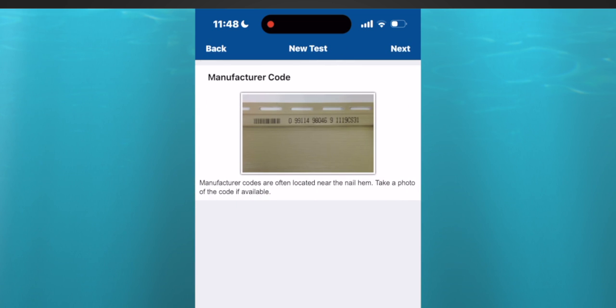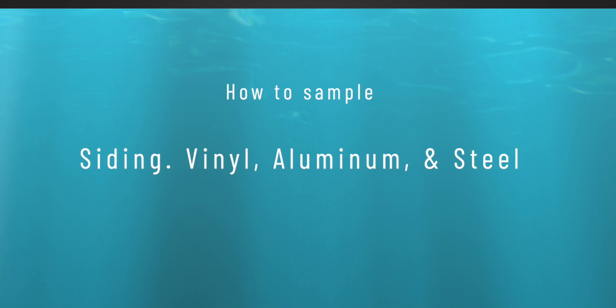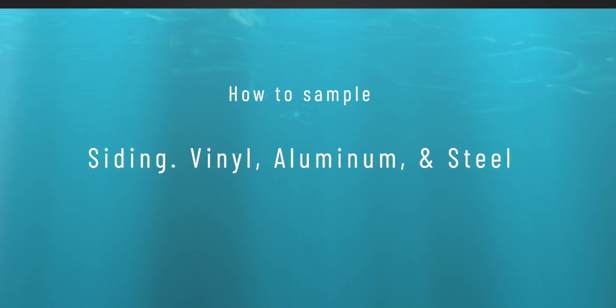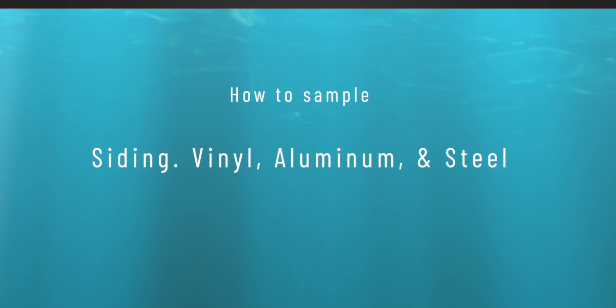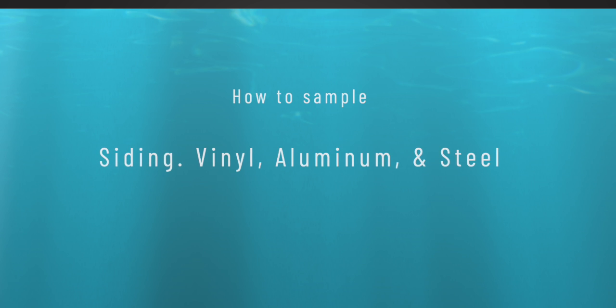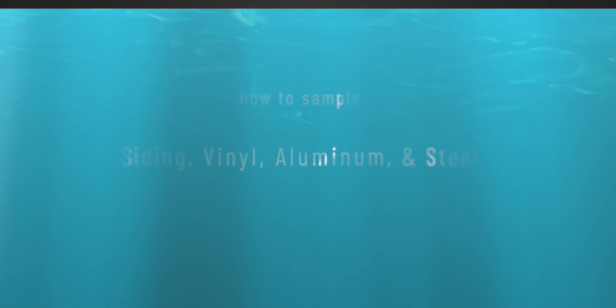Typically on this nail hem, there are manufacturer codes located near the nail hem. If you can take a photo of that nail hem, that would be ideal and offer the most concise and precise location of that vinyl siding to see if you can match it and replace the siding. And that's how you submit your siding material sample to the ITEL NOW mobile app.